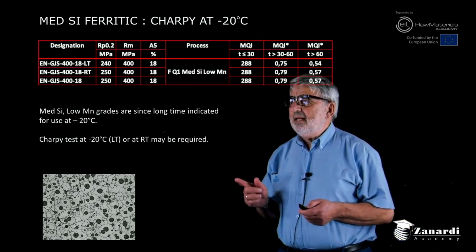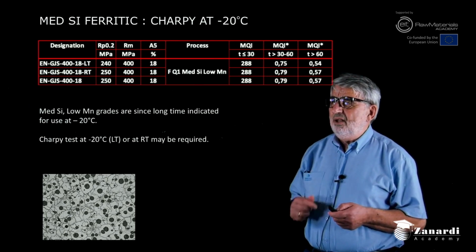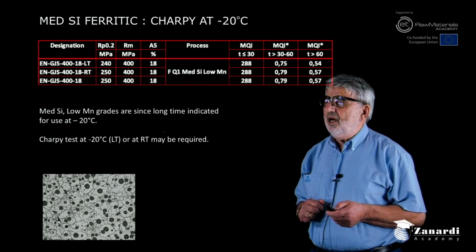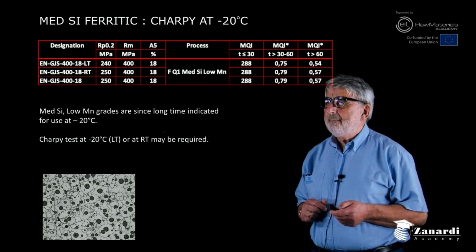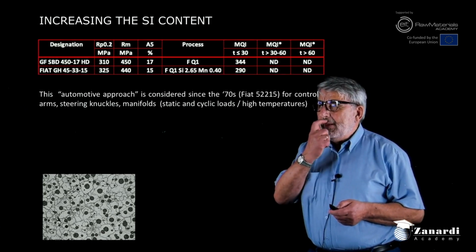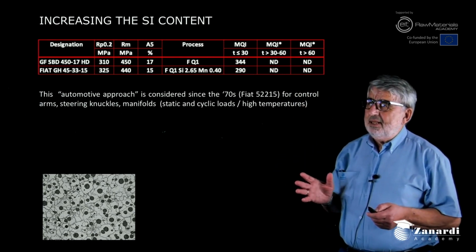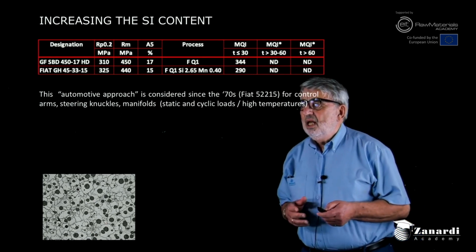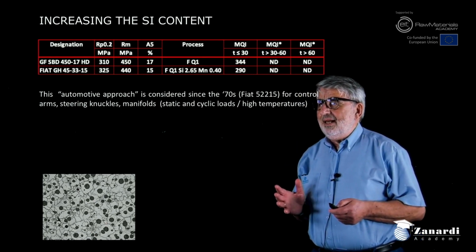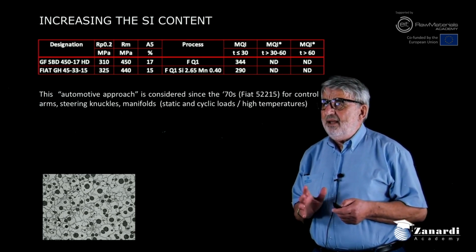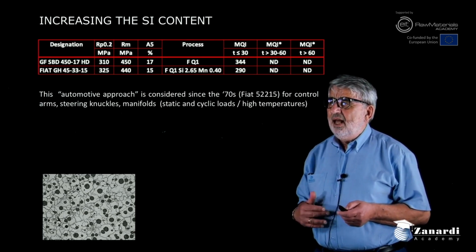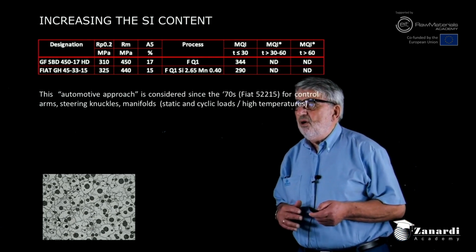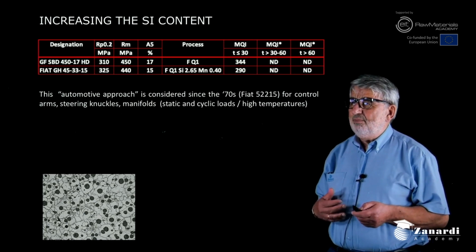Same, but at -20 with a different, lower Charpy energy required. Then, since the old times, some ferritic grades with a higher silicon content have been introduced in the market, especially for automotive casting purposes.